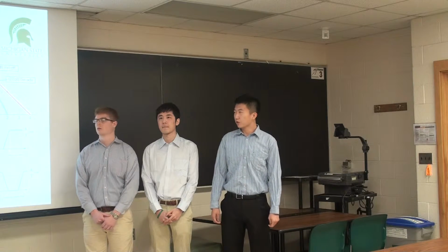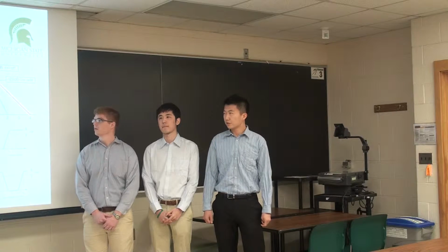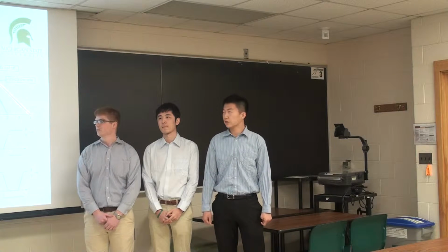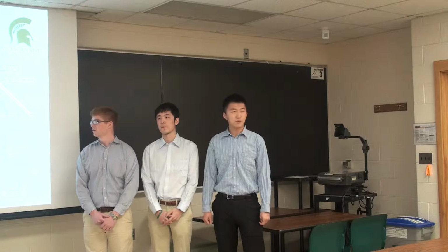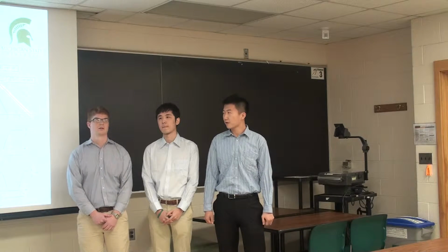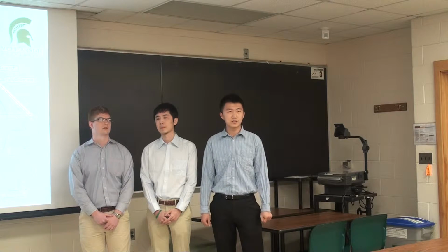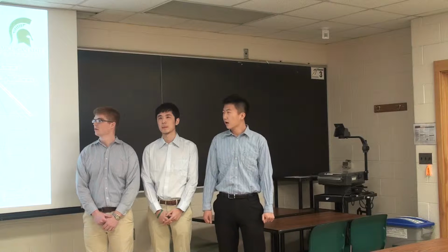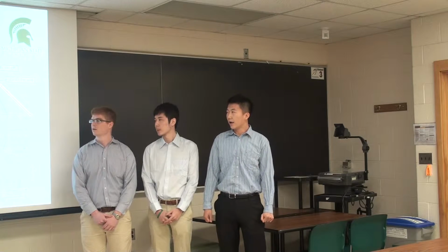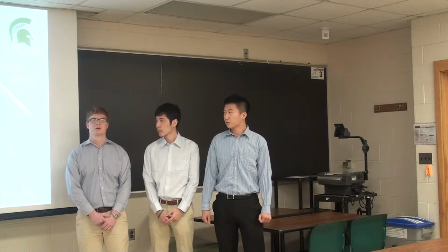And the equation we show on the PPT is the cutoff frequency of first order filters, which is 1 over 2 pi times the time constant. The time constant is dependent on the type of circuit. In this one, we can see the time constant is R times C, so we know this is an RC circuit. For example, if we want to use an RL circuit, the time constant would be L over R, and the cutoff frequency is R over 2 pi times L.